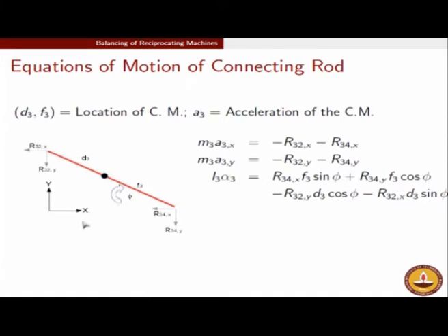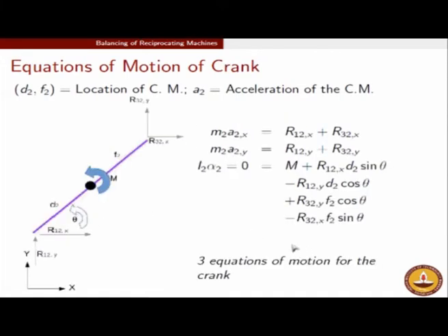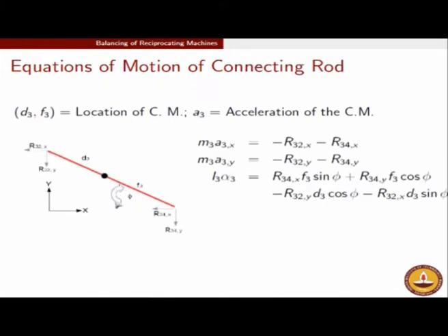The reason we have this discrepancy between the crank and the connecting rod is that our kinematic variable is theta in this direction, whereas it is phi in this direction. If you want your dynamics to be commensurate with the kinematics, then you should have it in this fashion. Otherwise, you have to take the kinematic variable in the other way if you wish to have a consistent moment sign between members.